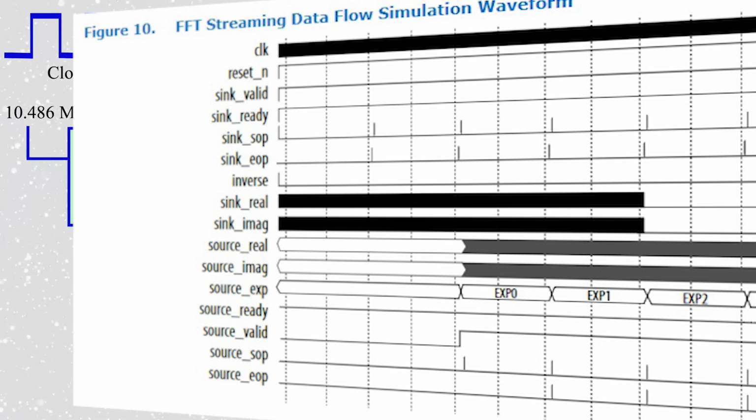And there will be a short latency period before the results of the FFT will start to emerge from the source output of the FFT block. Now, even though there's a latency period, that doesn't mean your output data is not continuous. It just means there's a short delay, a short latency period between the input data going in and the output data coming out, and that's usually very short, so it doesn't really matter that much.